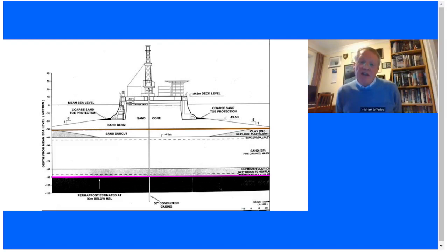And usually the seabed was soft clay, so we had to scoop out the soft clay because we were dumping some pretty hefty loads. I should say in terms of load, the horizontal load we were designed against was 50,000 tons, straight horizontal load. So we construct these sand-filled berms, and when we got the berms built, we ballast the platform down. I want to show you now how we are building these berms. That's key to our story.